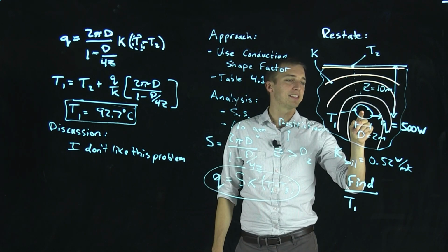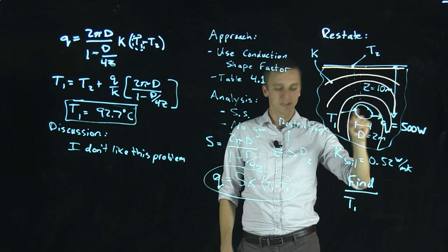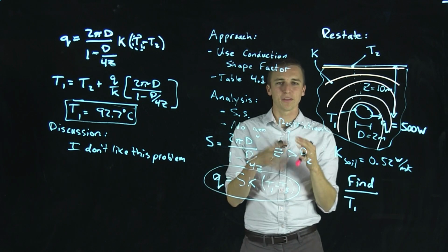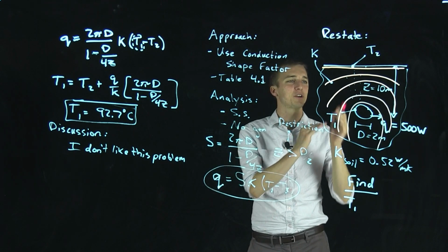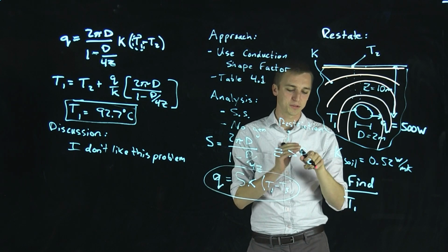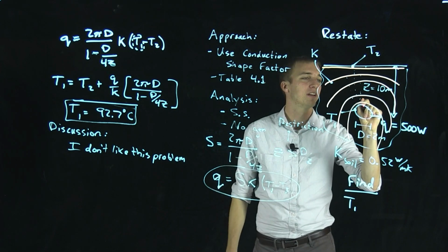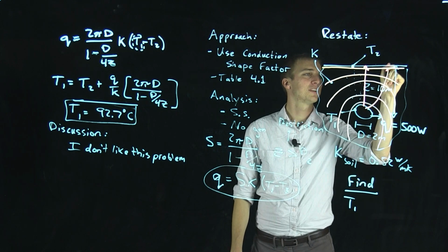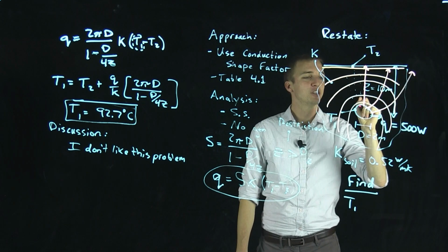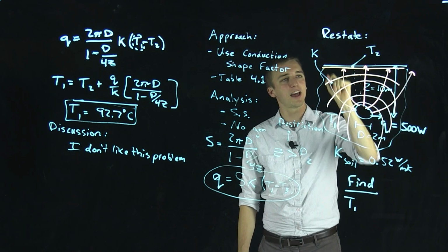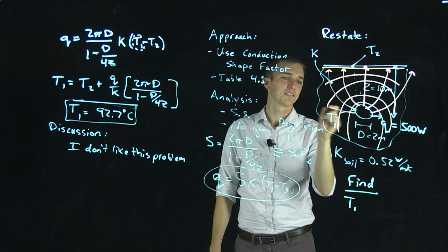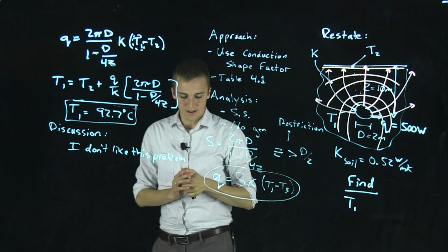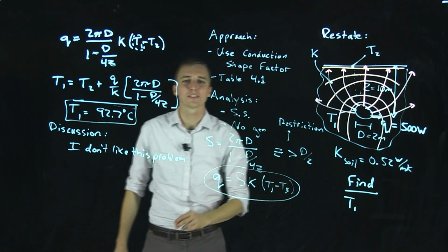And then we know that this is at an elevated temperature, and we're asked to draw heat rate lines, which, remember, the most important point is those heat rate lines are always perpendicular to our isotherms, or lines of constant temperature. So we know heat's going to go straight towards the surface, but it's also going to follow these 2D routes going off to the side and approaching the surface. Okay, that is the solution to our first practice problem in homework 4.